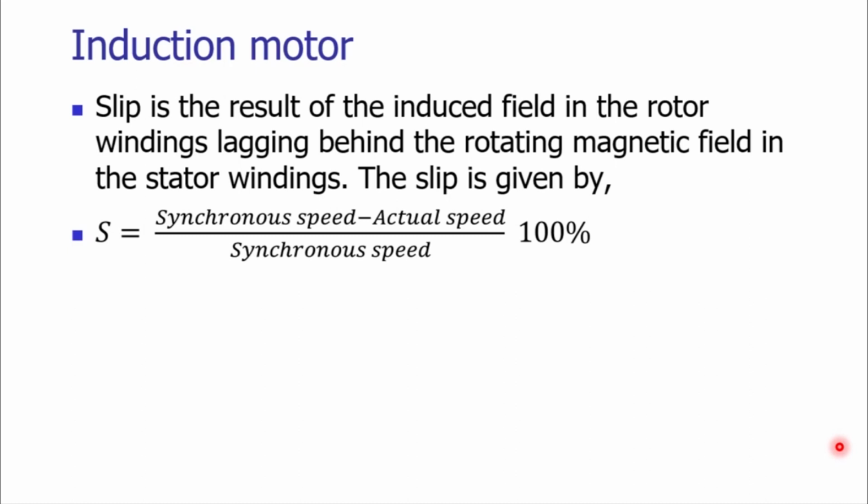It is expected that the rotor should follow the rotational speed of the magnetic field given by the stator winding, but due to the inertia of the rotor, due to many environmental factors, due to inaccuracies in the motor, the rotor will have a lag, it will have a certain deficit in the rotational speed. So that is called the slip in the induction motor.